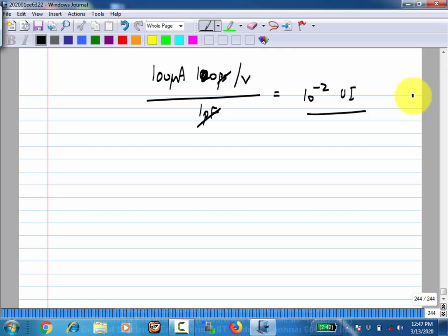So how many phases do you need in a cycle? 100. Your phase selection block should provide 100 phases so that you can pick this exactly. So it may be doable. It is kind of on the border of being doable, because the more phases you have to generate, the more you have to distribute, and that can become a problem. But you get the idea. If you divided your clock into 100 phases, you can pick one of them and do exactly what we were doing earlier.